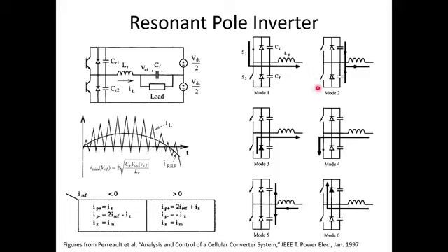What will happen then, when these two switches are off, the current will actually split between these two resonant capacitors, and the bus voltage will resonate down until the bottom diode turns on, okay. So now I've got the bottom diode on, okay, and I'm still delivering current to the output, but now the voltage across the inductor is negative, and the current's going to slew down in the inductor. But notice something. As long as this diode's on, what is the voltage across the bottom switch?